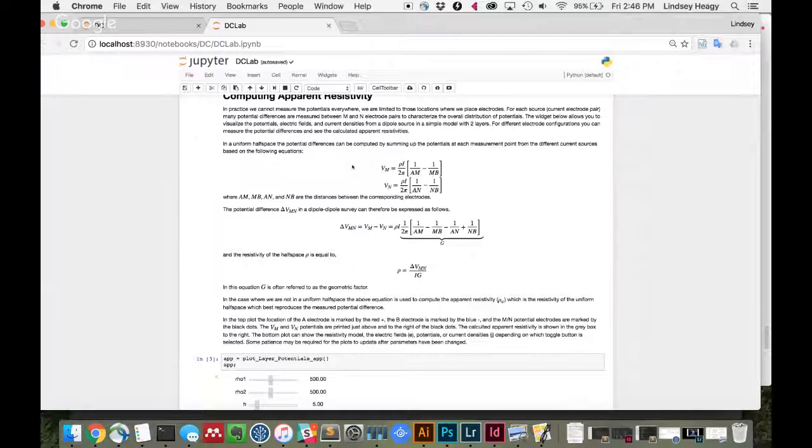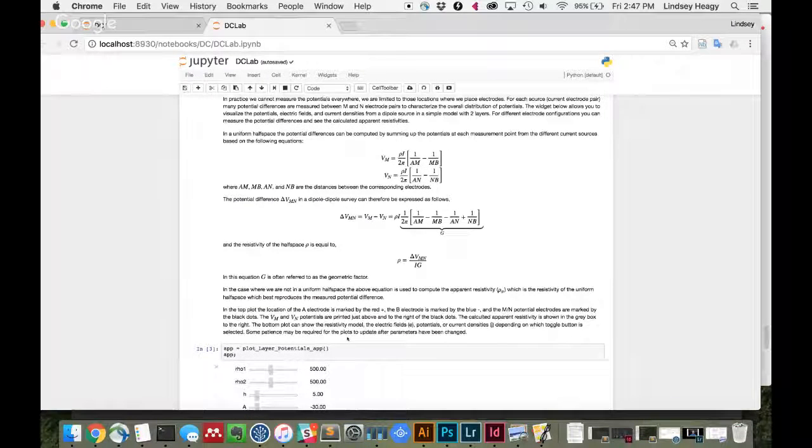So if I now make my 4 electrode geometry, so here's my A electrode, and here's my B electrode, okay? If I look at some position here, M, then the voltage at this particular point, which we call V sub M, is equal to the voltage that I get from here, which is rho I over 4 pi R. And now I'm going to subscript this with a distance, so I'm going to say that's A times M. So I'm going to keep track of all my electrodes.